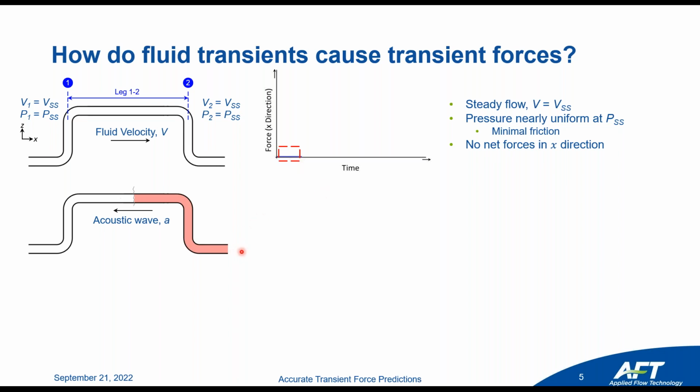At some time later, we're going to talk about somewhere downstream here to the right, a valve is going to be closed. Let's talk about an idealized valve where that valve closes instantly and it sends a surge wave or a water hammer wave moving to the left. So it's moving in the opposite direction of the fluid velocity, and it's moving at the sonic or at the wave speed A, which is close to the speed of sound of the fluid.